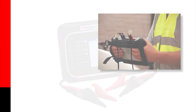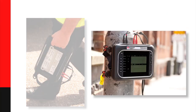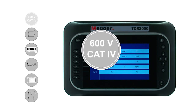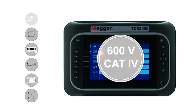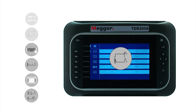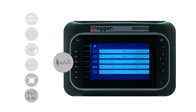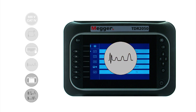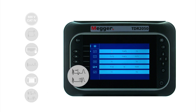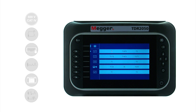The Megger TDR2050 is a dual-channel, dual-trace TDR with a high-resolution color screen for locating faults on paired metallic cables. The instrument has Cat4 600-volt input protection built in, step and pulse TDR options to see both near and far-end faults, trace tagging for recording circuit ID, distance-dependent gain to minimize signal attenuation, a trace hold feature for instant trace comparison, auto-find and find-end functions allowing speedy fault identification.